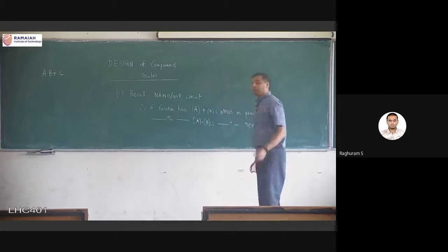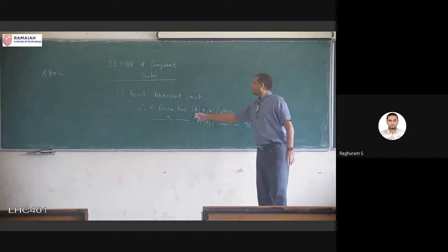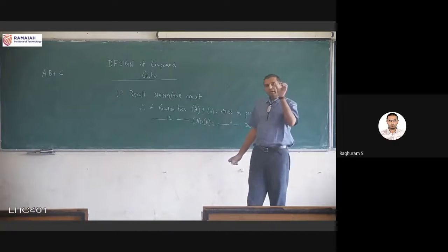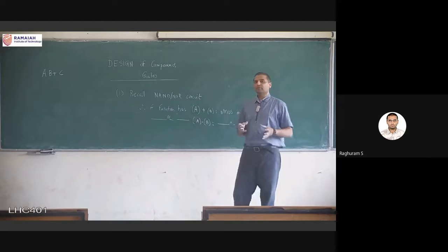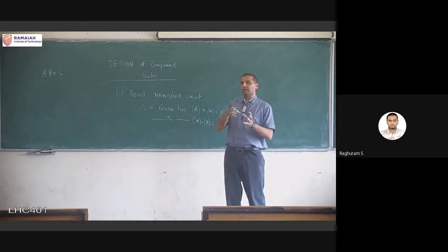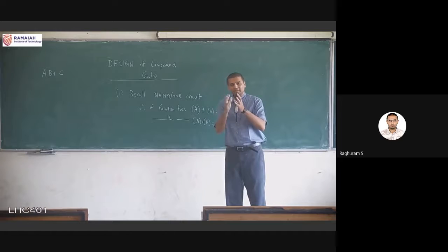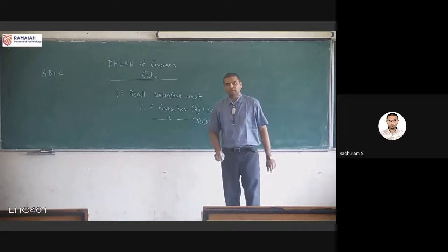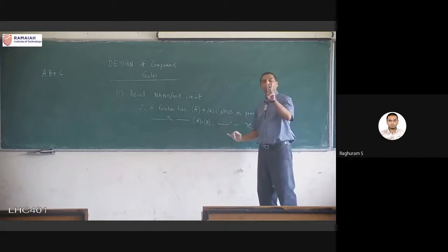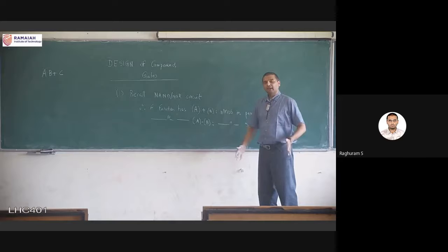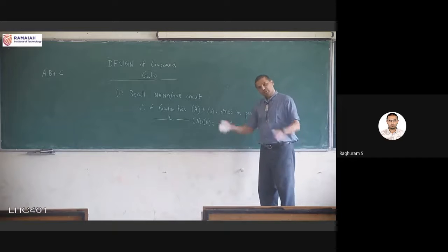And in the NOR gate, when I have A plus B, and I have put the bracket here because instead of A, I can do A plus C also, not necessarily just A, we will not worry too much about that, but whenever I have two terms being ORed, I have to put two NMOS transistors in parallel, and automatically where I put the NMOS transistor, it will be in the pull-down network, it cannot be in the pull-up network.